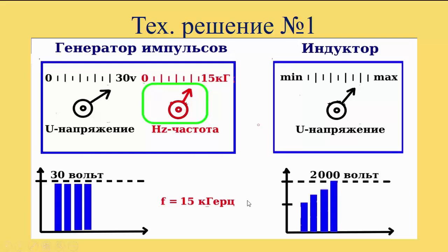So we move on to frequency selection. Through manipulation and frequency selection, we found that we have a voltage resonance at a frequency of 15 kilohertz. Again, the numbers are conditional. And as a result of that resonance, we've got 1000 volts going up to 2000 volts.